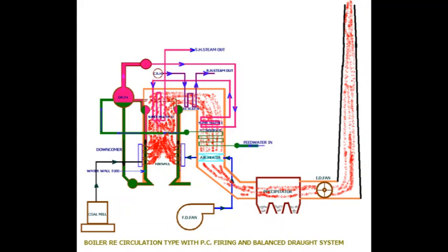Besides that, gradually concern for the environment evolved, and how to arrest the dust particles and other toxic materials from the flue gas came up. So electrostatic precipitators, mechanical dust collectors, fabric filters, and selective catalytic reactors and non-selective catalytic reactors were introduced for control of SOx and NOx.